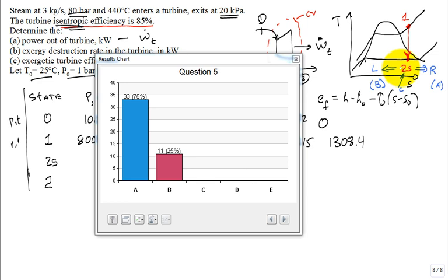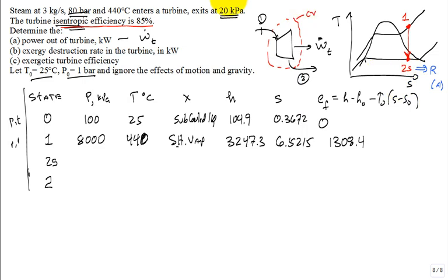What's going to happen if you do have some irreversibilities? There's going to be some entropy generation. What happens to that entropy that's generated inside the turbine? It has to be swept out with the outgoing fluid, in addition to the incoming entropy. So S going out is higher. It's going to be off to the right. The actual state, maybe it's right here, and maybe we show a dashed line going down to 2 actual, state 2 actual. Make sense? All a review of thermo 1.